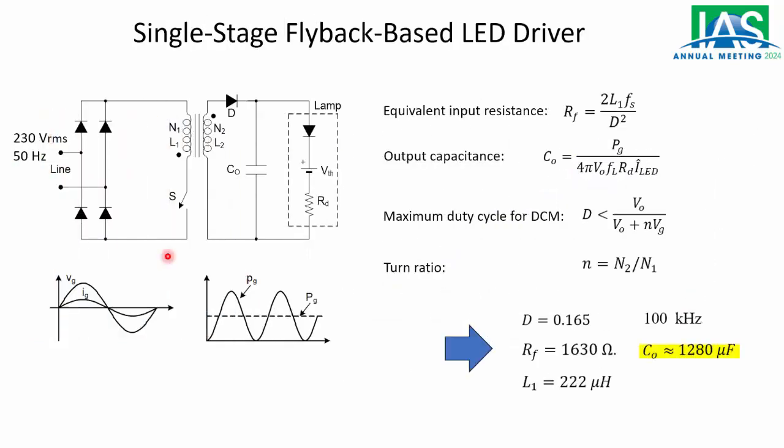So this slide summarizes the design of the single stage flyback based LED driver. As we know, we have approximately after the filtering at the input, a sinusoidal current at the input and in phase with the input voltage, and this is the instantaneous power that we have at the input.